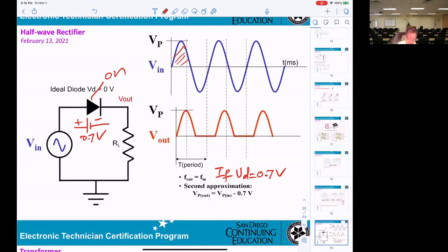So at the output here, you can get 2 signals. One will be DC, and another one will be AC. So when I draw it, I can draw for you right here. Minus 0.7 volt DC. If you're looking on the scope, you can see you get minus 0.7 volt.